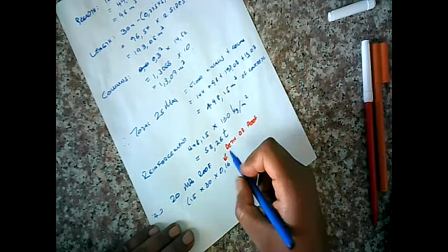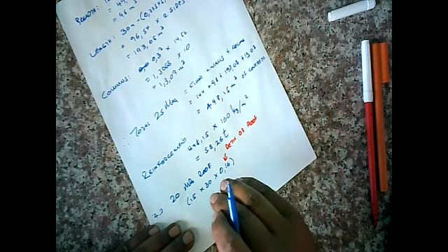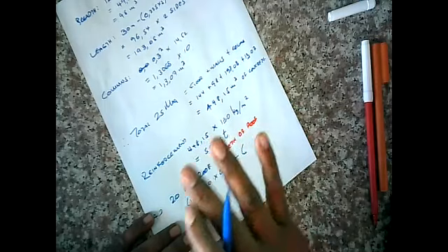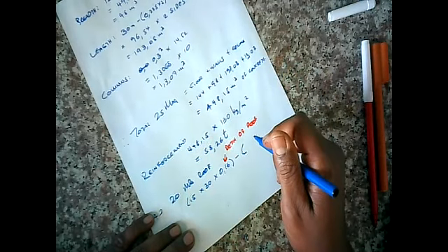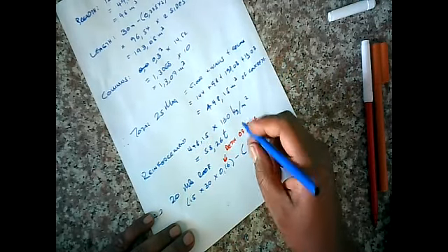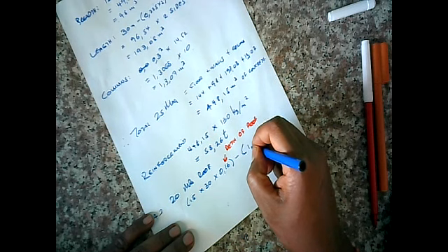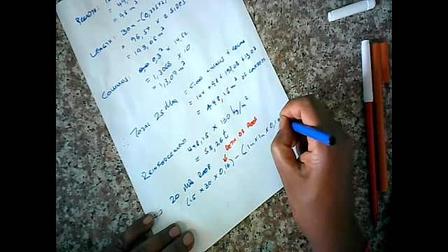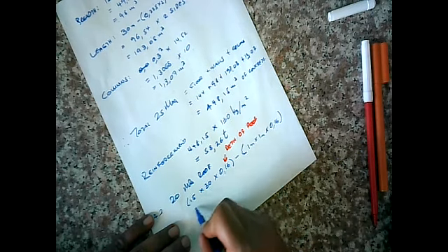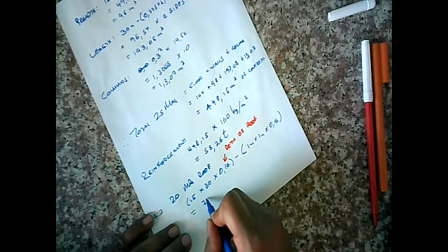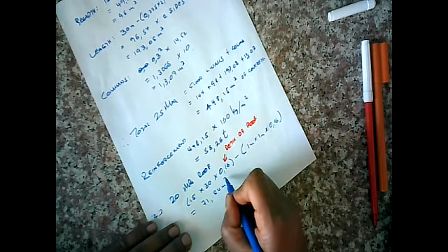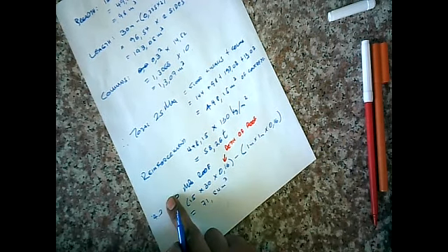All right, but also within that roof, there's a hole, a manhole. So it's a hole basically, so it's not going to require concrete. So we need to take that off. We know the dimensions of the hole is 1 meter by 1 meter. The thickness is 0.16. And you get a volume of 71.84 meter cube of 20 MPa concrete.